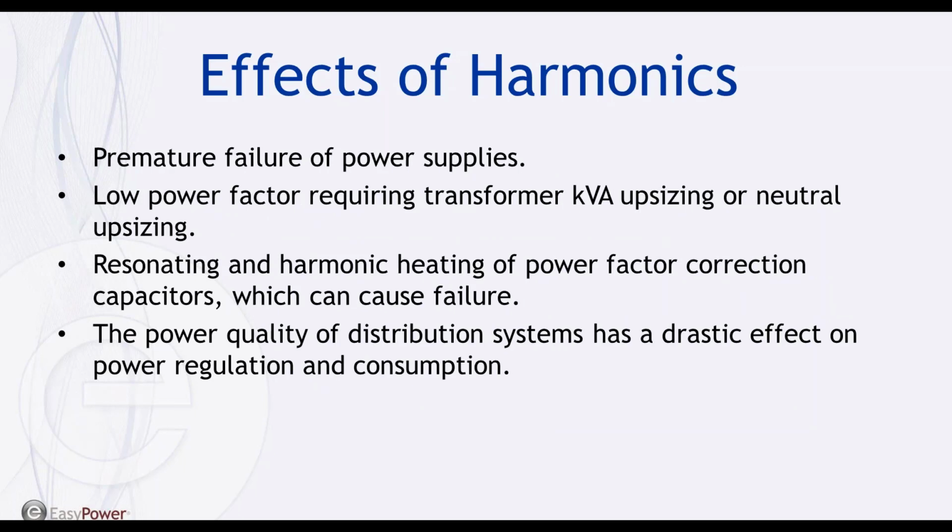Going on with the effects of harmonics, harmonics can also result in premature failure of power supplies due to distortion of the supply voltage. Harmonics can also result in a low power factor, requiring a transformer to be upsized in kVA or neutral upsizing. Harmonics can also cause resonating and heating of power factor correction capacitors, which can cause failure. The power quality of distribution systems has a drastic effect on power regulation and consumption.